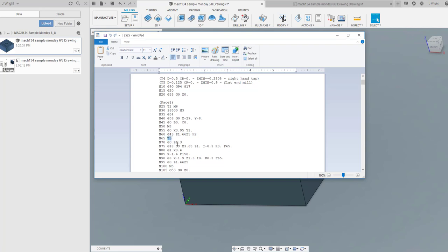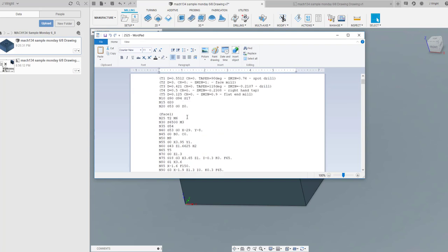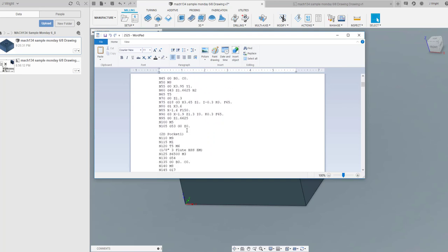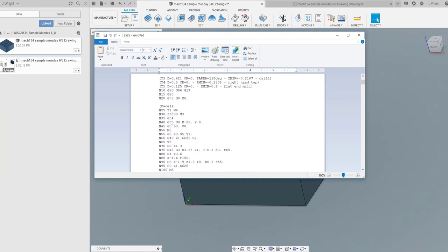It's going to preload tool 5, and on our umbrella carousels we don't have that option of doing that. But we don't care. It's not going to hurt anything. It's not going to be in our way. The only place it's going to cause us a problem, so tool 5 is our next tool that runs. So here you have turn coolant off, optional stop, go to tool 5. The only time it can possibly cause a problem is if you're at the machine and you type in T5, arrow down, and you search for T5, it could possibly, actually it would find this T5 first.